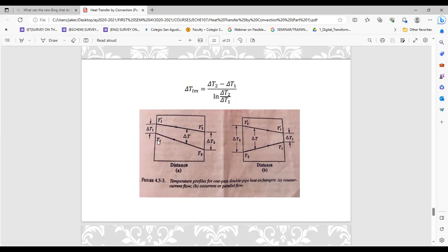And this will be your delta T1 and this will be your delta T2. So if you intend to recall this again, you may take a picture before we go back to the Jamboard where we're going to place in our solution. So you will not be confused as to the representation. So your oil will have T sub 1 prime and T sub 2 prime for its inlet and outlet temperature based on this representation of countercurrent flow for a double pipe heat exchanger.